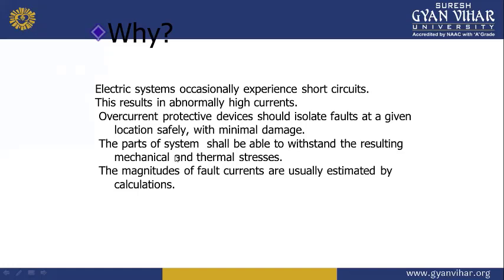Now, the power network comprises synchronous generators, transformers, lines, and loads. Although the operating conditions at the time of fault are important, the loads can be neglected during the fault, as the voltage dip is very low, so the current drawn by the loads can be neglected in comparison to fault currents.